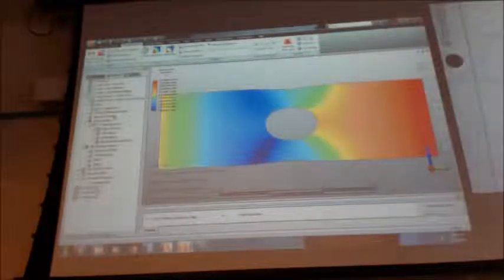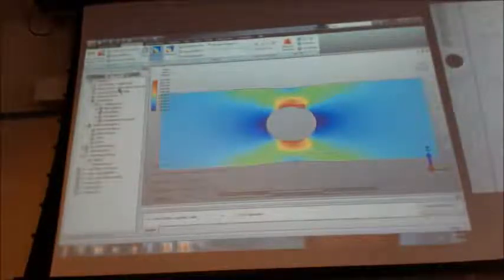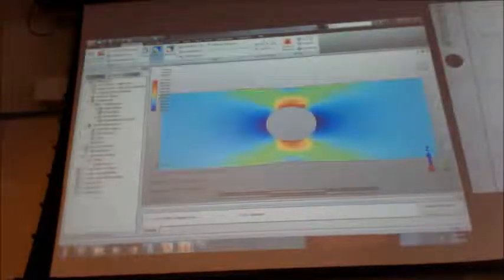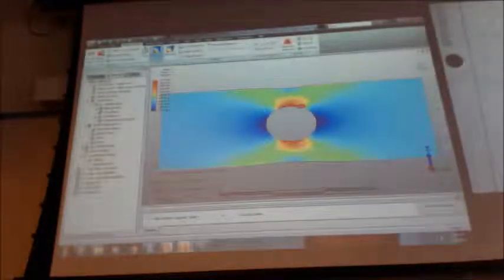So the way I ended up constraining it is, if you constrain one node on the neutral axis, then you're going to affect the movement the least, because you're on the neutral axis. And there's your results. And I felt like it provided better results than constraining it anywhere else.